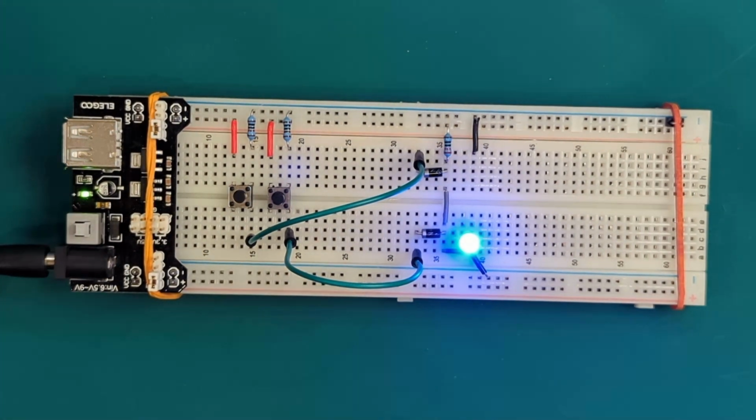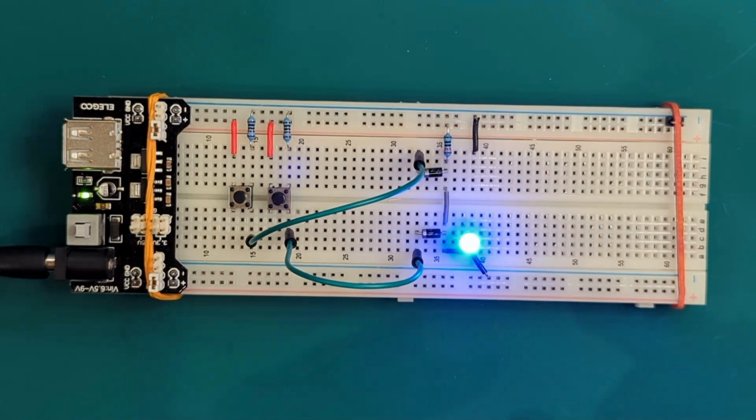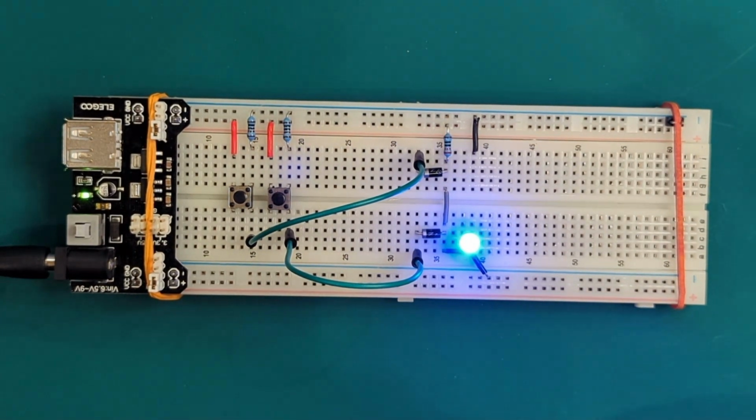What I'm getting is not what I expected, so follow me along as I debug this. When I get an unexpected output out of a system, the cause for it usually falls into three categories. The first one, the system doesn't do what I actually expect. The second one, the system actually works, but I'm feeding the wrong data. And the third possible cause is that the system is actually working, but my expectations are wrong. That is, I miscalculated the output that I should be getting. The AND function is simple enough to feel that I'm likely to know the right result, so I'll discard number 3 now. And I usually prefer to check number 2 before number 1, especially if it's easy.